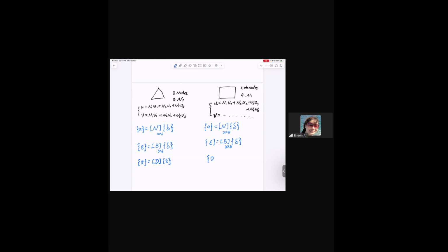And for rectangular element, we use the same equation, right? And don't forget this D matrix is related to the type of those 2D problems. If this is a 2D plane stress problem, you have to select the D matrix for plane stress.